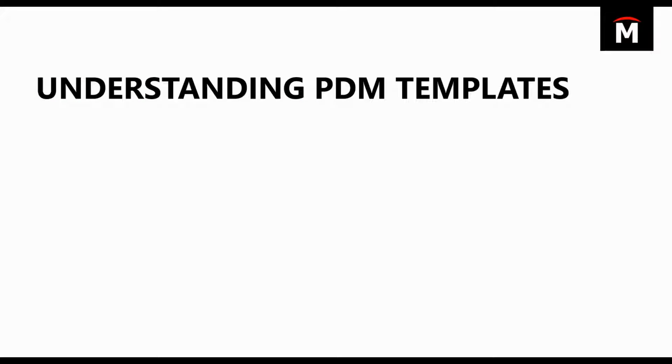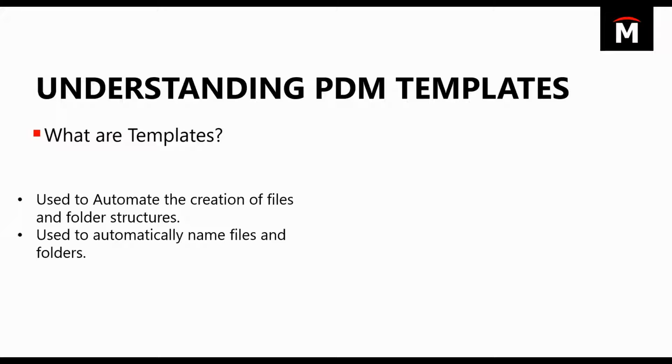Okay, so let's try and understand PDM templates in a little bit more detail. So what are templates? Well, templates are a way to automate the creation of files or folder structures inside of your PDM vault. During this creation process, you can also automatically name files and folders. You can grab custom variables that go into the data cards for either the folders or the files.